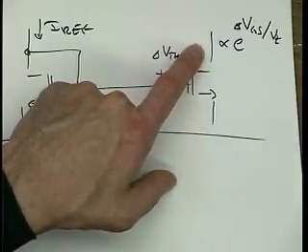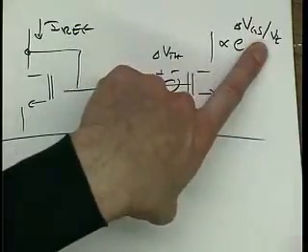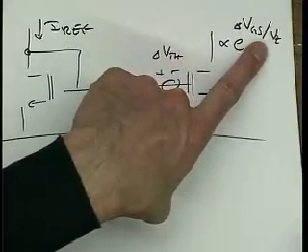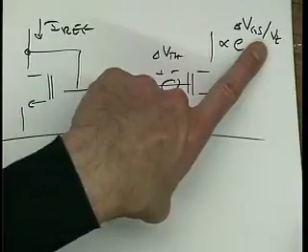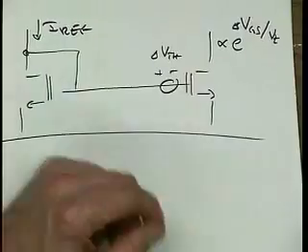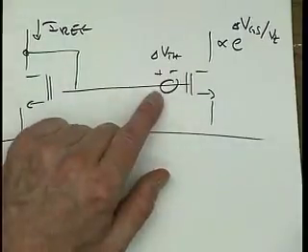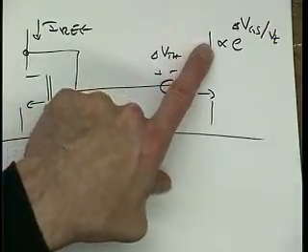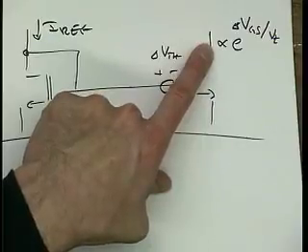In this MOS device, we have this other factor of n in there, so instead of 60 millivolts, we need n times 60 millivolts, or 90 millivolts, to change the current here by a factor of 10. Okay, we're not going to have a threshold mismatch of 90 millivolts here, right? That would be a little bit extreme. But we also don't want to have an error here of a factor of 10 in current, right?